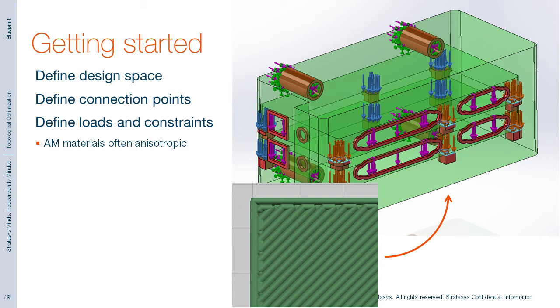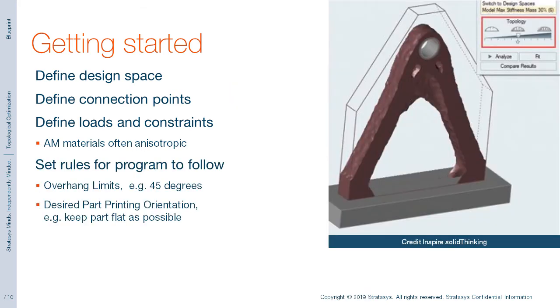One thing worth considering is few topology optimization codes are able to cope with anisotropic materials. The unfortunate thing being that almost all AM materials are at least slightly anisotropic. So when defining your material, consider how to approach this. The obvious common fix is to use the lowest material properties, often in the z-axis, as the global isotropic properties for the simulation.